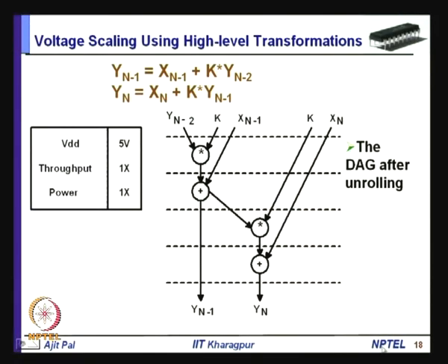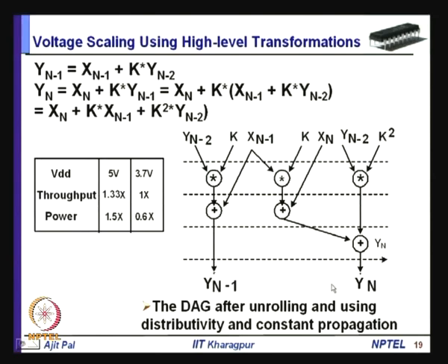Here it requires 4 clock cycles, here it requires 3 clock cycles. Instead of that, what can be done? The time required for 3 clock cycles can be made same as that of time required for 4 clock cycles by reducing, how can it be done? By reducing the frequency and simultaneously reducing the supply voltage.